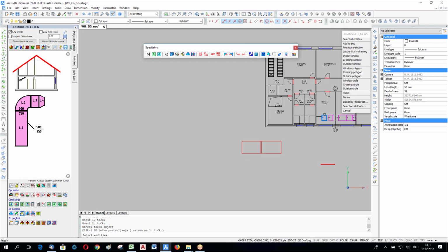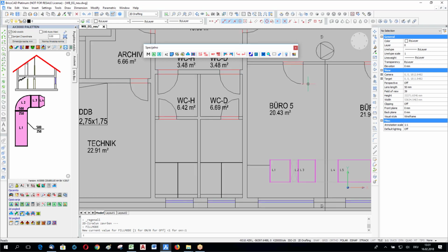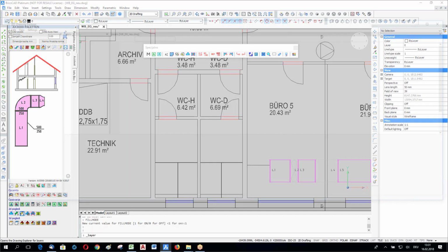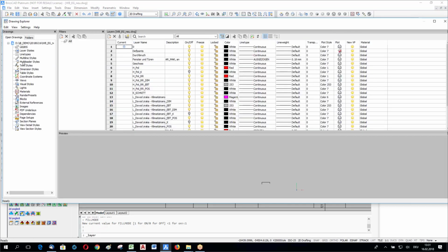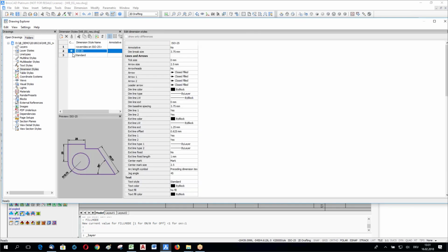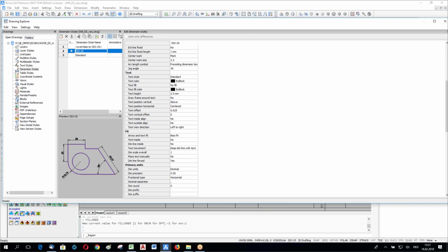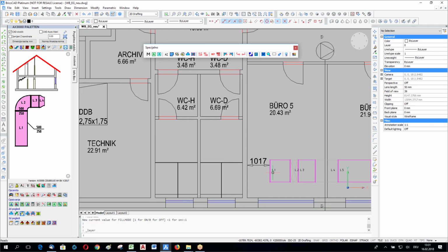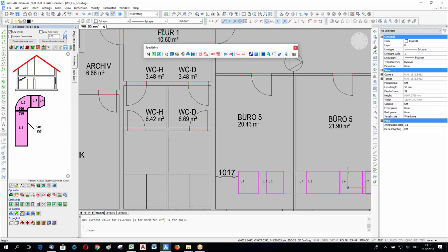And then I select maybe only one duct. Only one duct is highlighted, reference height is the same, and I want to change these dimensions a little bit, text style, dimension style, activated one, enlarge, okay. Awesome. The first point was in the corner. The same was done here.